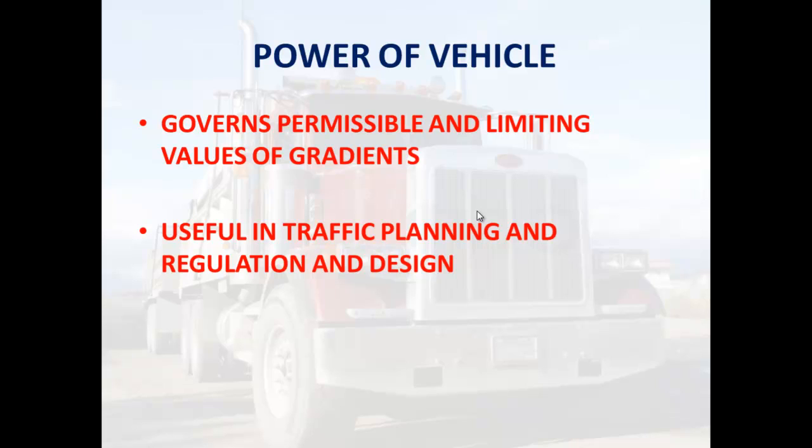And if the power of the heaviest standardized vehicle is less, the gradients we can provide should not be that steep. I hope you're getting me. The power of the heaviest vehicles and their loaded weights govern the permissible and limiting values of gradients on the roads. Isn't it? It's common sense.